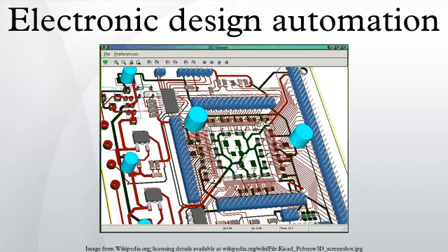Manufacturing preparation. Mask data preparation, MDP, generation of actual lithography photomask used to physically manufacture the chip. Resolution enhancement techniques, or RET, methods of increasing the quality of the final photomask. Optical proximity correction, OPC, an upfront compensation for diffraction and interference effects occurring later when the chip is manufactured using this mask. Mask generation, a generation of flat mask image from hierarchical design.